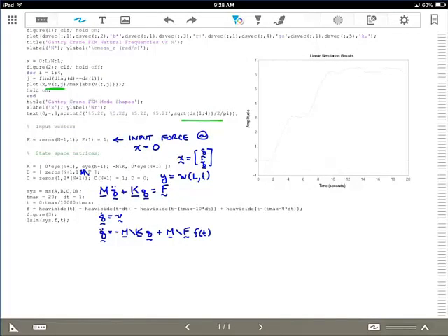Okay, so basically we want to run a simulation, and it's kind of neat that with these kinds of systems you can actually do what's called input shaping, where you can give a certain input to the gantry, and of course the objective is to move the payload from, say, position 0 to some other position, but you'd like it to arrive there with as little vibration as possible.